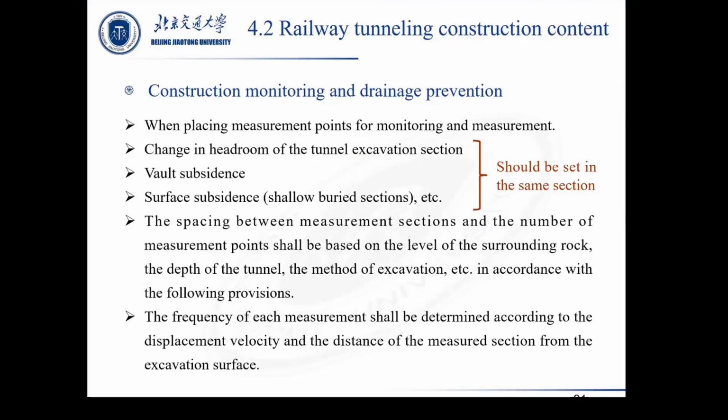According to the following revision, the frequency of each measurement item should be determined according to the displacement vector and the distance of the measurement section from the excavation surface.